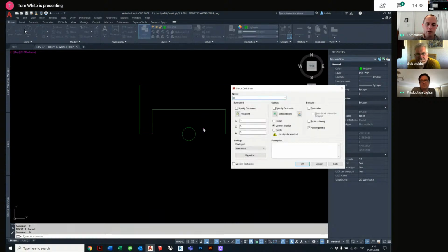So in this circumstance, I would like to do a section of a deck. I've selected the block command, which has brought up this dialog box. I've named it something. If at all possible, it's always nice to name a block something. You don't have to, but it's really convenient to do it, because in the same way as a printed drawing ideally would tell a story, in an ideal scenario, if I'm not working on a job anymore and Dom is now moving on to it, it would be really handy if Dom was to click on something and he could be told instantaneously what it is, even if it doesn't look like a section of a steel deck. I was talking to somebody, Dickie, earlier in the week, and it is really important.